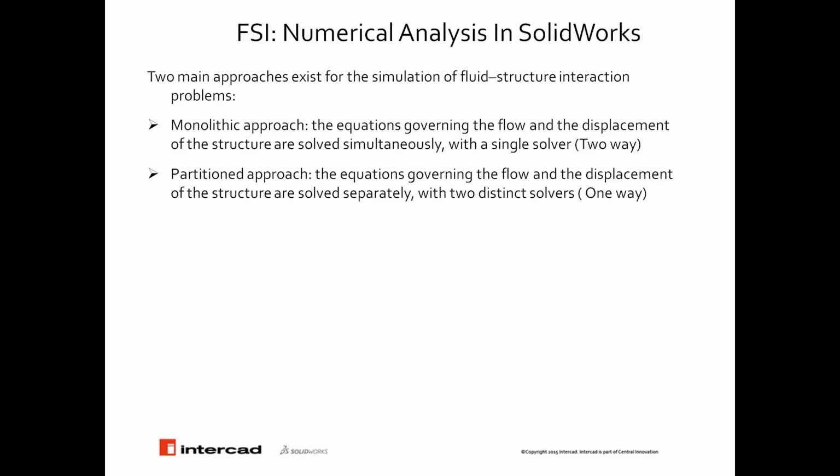In most applications, we use two-way FSI because the structure is deforming or displacing significantly. But for some applications, such as wind loading on a big structure, we can assume that we have a steady-state sort of flow in any direction that keeps continuing, and we can simply get the response of the structure due to that wind load, with no oscillation or other issues.